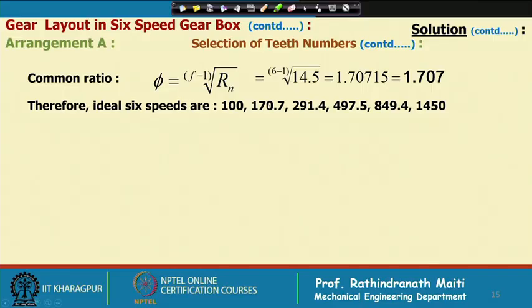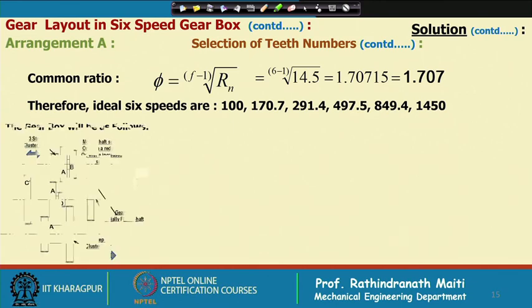As already mentioned, with such a speed, suppose it is used for a lathe and a stock from 200 to a minimum diameter of maybe 10 millimeter is being machined. So, that might be in different steps. The machining speed, cutting speed can be more or less the same for different steps. Okay. So, we will now look for the gear ratio so that we get such speed. Definitely it may not be an exact ratio, may not be possible.